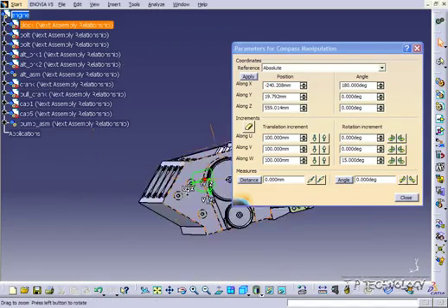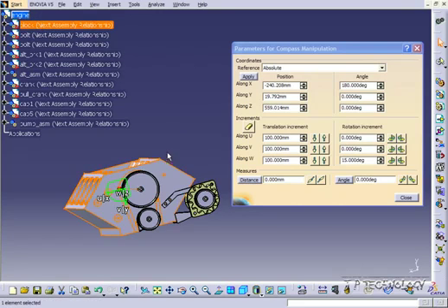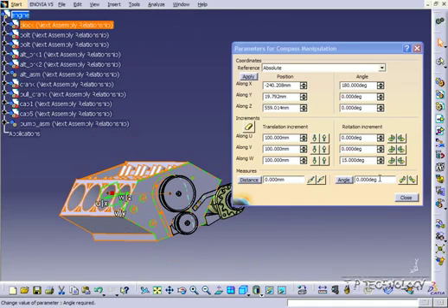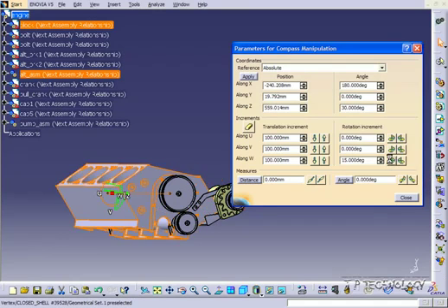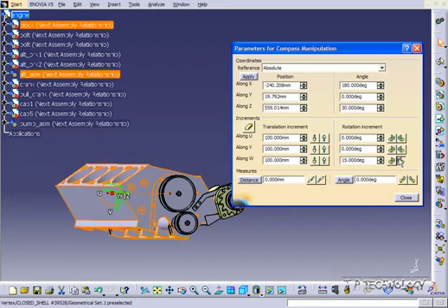So now again, you're able to go through the assembly and use the hierarchy system and pick which parts or assemblies you want to move. So to start off, let's move just the engine block. So let's double click engine, just highlight the engine block, and we have it rotating around the W axis at 15 degrees. So let's just try it out, see? And you can see how the whole block is rotating 15 degrees every time we click.